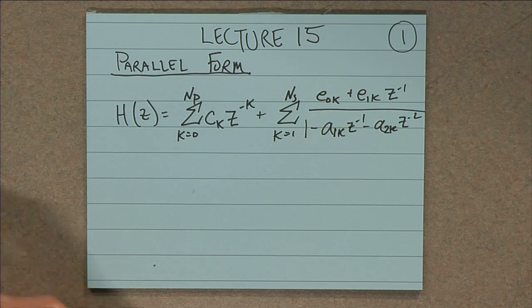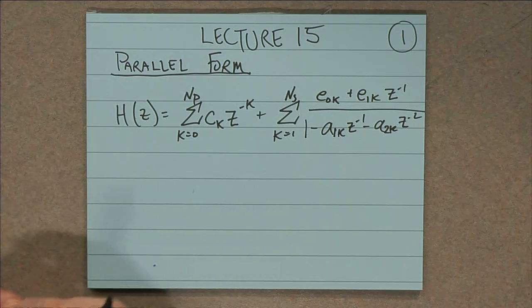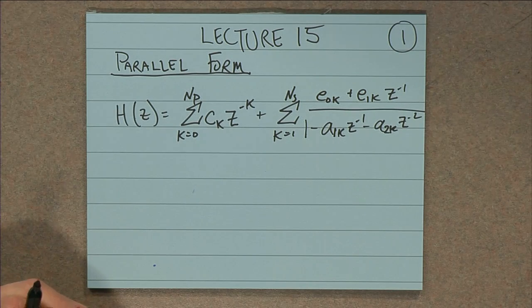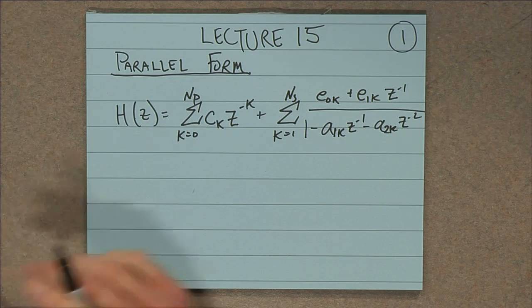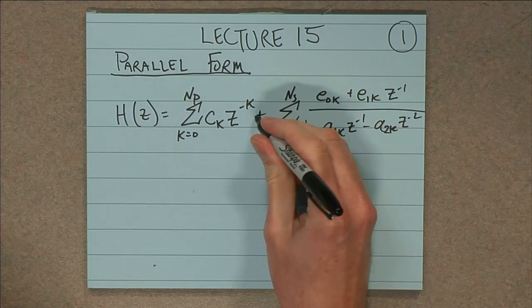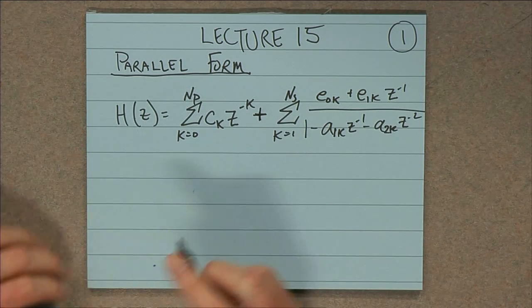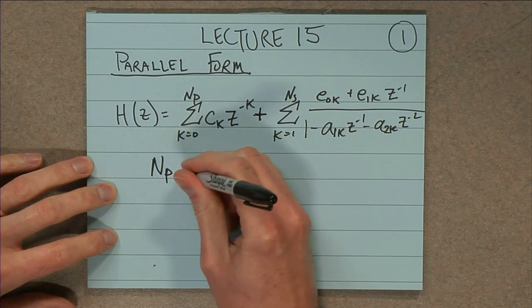Typically you can control the gain of the signals, which means you control the dynamic range through the processing. And also, on average, your tolerance compared to the number of bits you have in your arithmetic seems to work a little bit better with these second order sections. So we're going to stick with that for our discussion.